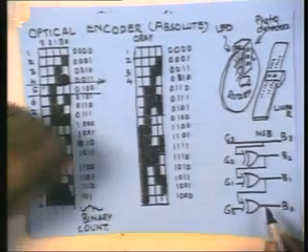So one can easily build this kind of circuit in the hardware and attach it to the encoder, which has got gray level inside. Inside you will always like to have gray level. For the output, you can give an option of having either gray output or binary output. Okay, so these are absolute encoders that we have talked about.